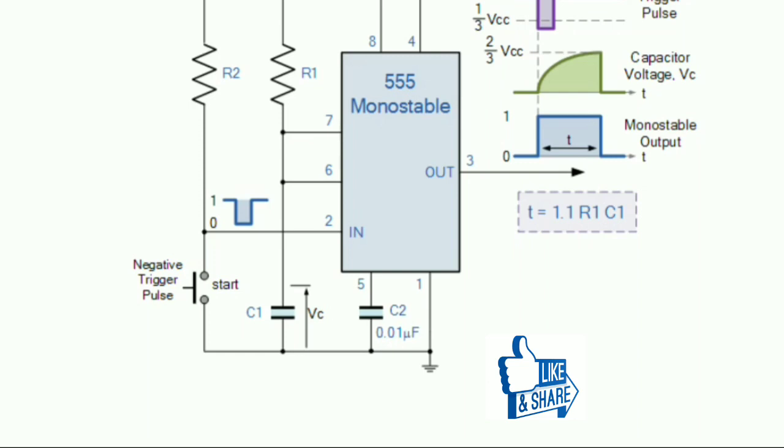Okay, so after the capacitor discharges, we are getting the output 0 again. And then again you apply a negative trigger pulse. When the negative trigger pulse is applied, it crosses 1/3 VCC, then again the capacitor is going to be charged.